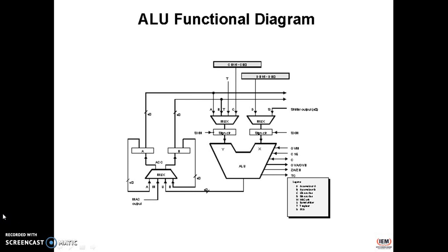Under the central processing unit, the C54x CPU contains a 40-bit arithmetic logical unit, 2 40-bit accumulators, a barrel shifter, a 17 x 17-bit multiplier, a 40-bit adder, and a compare, select, store unit, which we call the CSSU. It also has a data address generation unit and a program address generation unit.